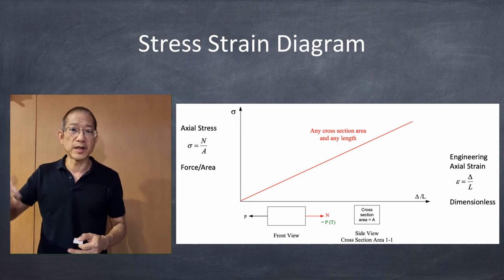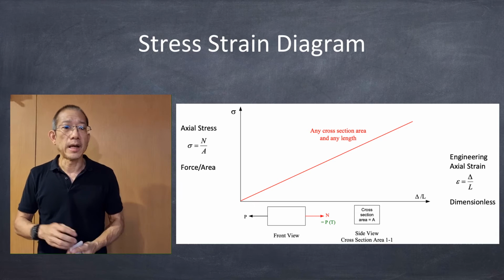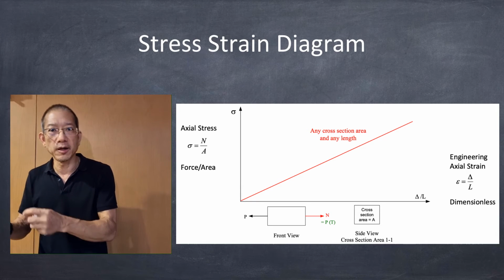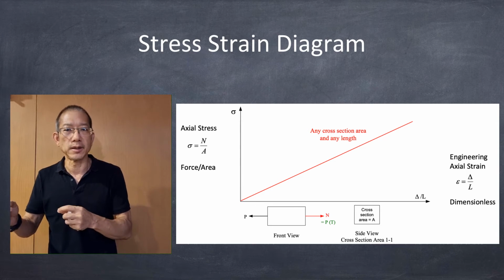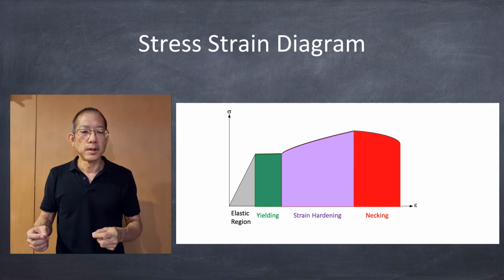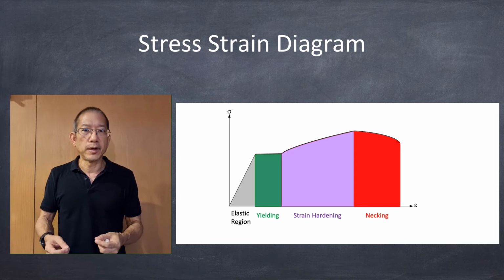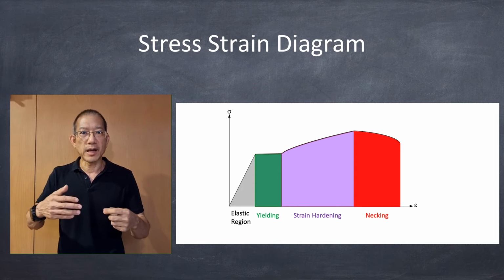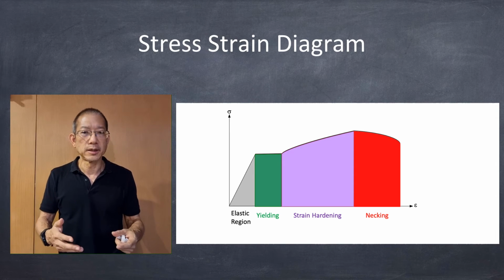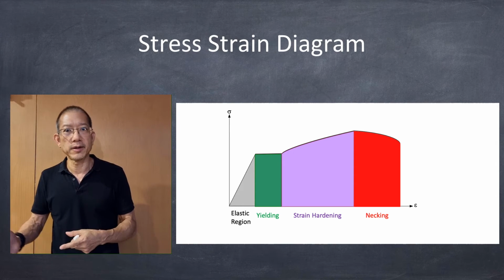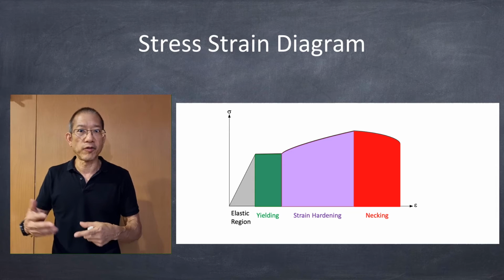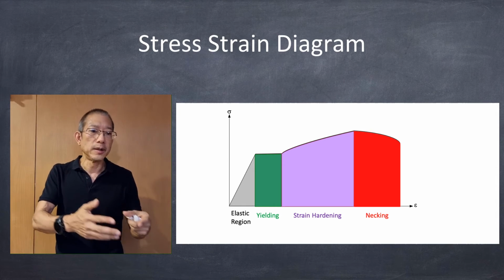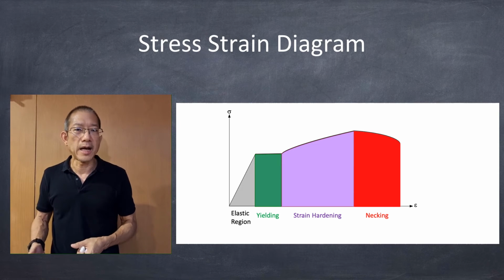So they have this nice graph, the same curve all the time, and this becomes what we call the stress-strain curve, and it's quite consistent for one material, right? If we pull it further in a test or something like that, and we pull it until it breaks, then we have a full graph like this. I believe you're going to study further in the textbook because there is a lot written, but then we can separate it into different zones: elastic zone, the yielding, and the hardening zone.